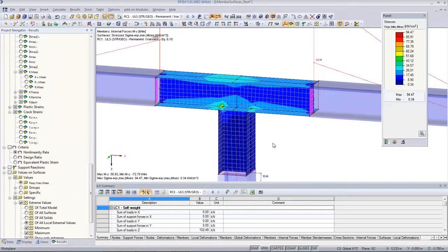The way the software works, it compares the existing stress with the limit stress for the yield stress of the material, and then has an algorithm that reduces the stiffness and the elasticity modulus of those elements. Because we can only reduce the stiffness of the entire finite element, we cannot evaluate, or we should not evaluate, the result separately in each node of the finite element.